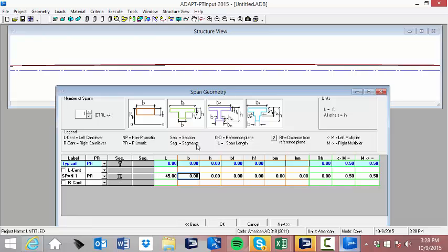The dimension parameters are illustrated in the sketches above the input table. So for an I and an L section, we're using this third sketch to reference from. The B dimension is going to be the dimension of the web. So for this dimension, we're going to say this is 12 inches. The total height of the I-beam we'll say is 36.